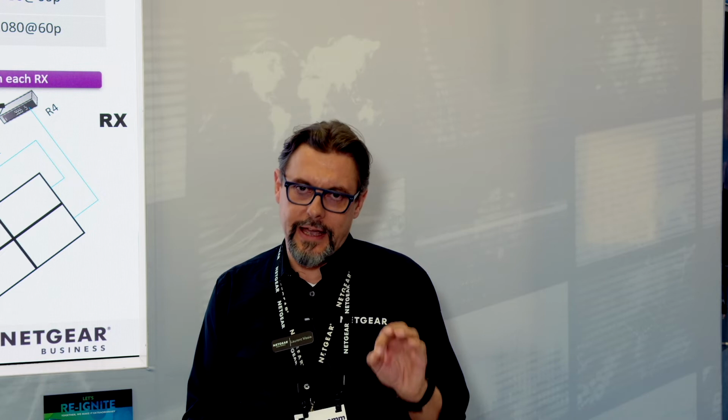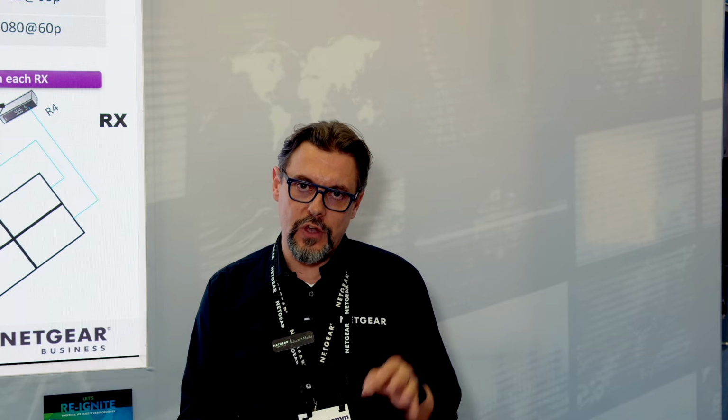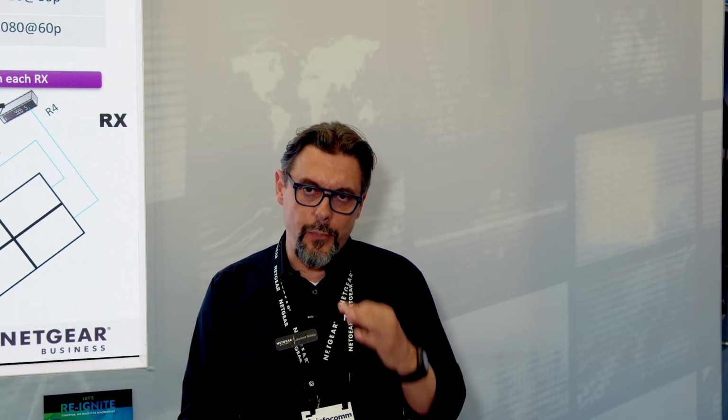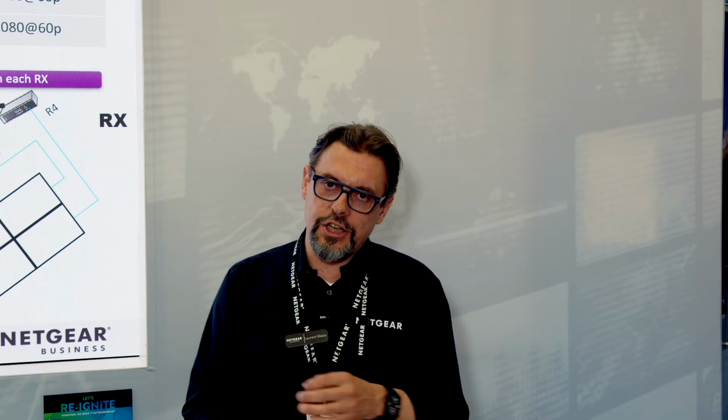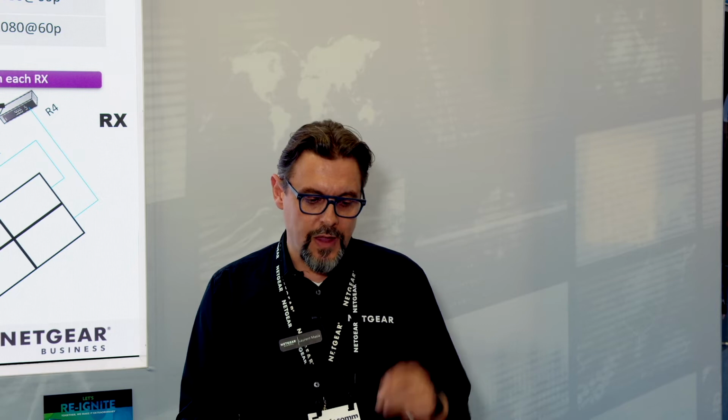Well, this SDVoE controller will send instructions to your endpoints so that the endpoints can put IGMP to work, because the switch, which is again the fabric, doesn't listen to the controller. This switch will just work per the IGMP protocol with encoders and decoders on the network. So follow my logic: you drag and drop T1 to R1, and the controller just sent the instructions to your video endpoints.